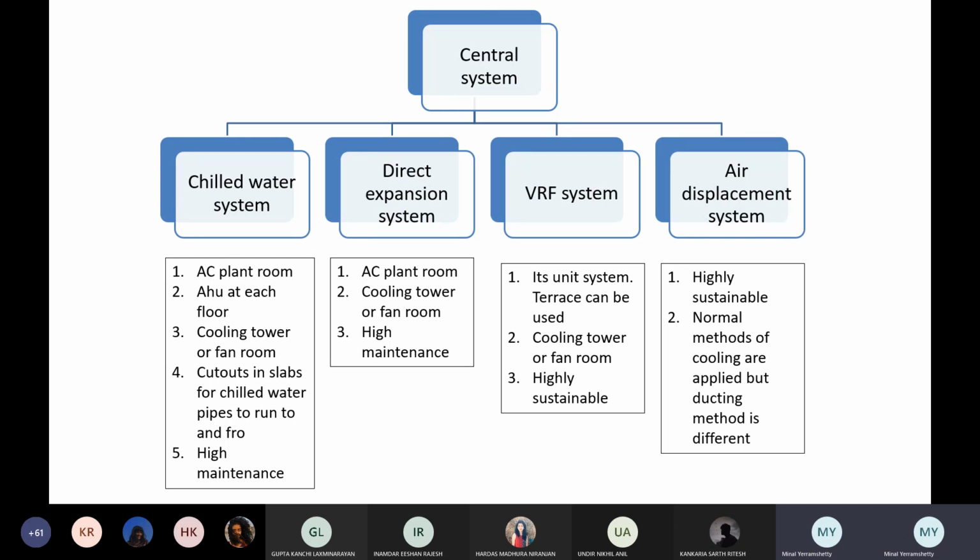What happens is you have this air and you are blowing a fan on it. This chilled air is then taken via ducts to the area. Sorry, my mistake, it's not hermetically sealed, it's not sealed at all, but somewhere you will have to supply the air. Then the air from the room comes back, the return air is brought back to the basement, and it doesn't have the AHU. It comes back to the basement, the same box, the same chiller, where again it gets chilled, and then with the help of the fan it goes back again.